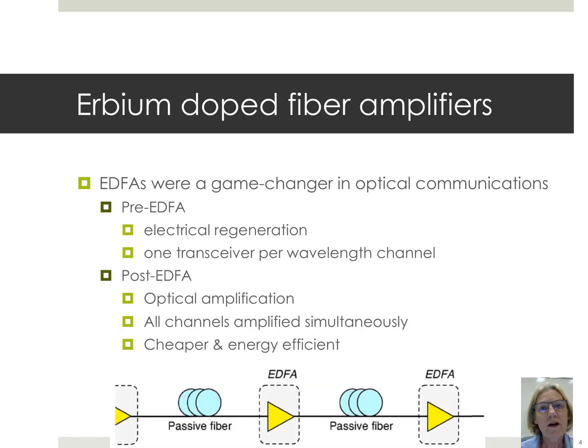So that was what I would call the first generation of optical communications. Then there was the development of a device known as the Erbium doped fiber amplifier, or EDFA. And EDFAs were real game changers in communications. Before the EDFA, we had this electrical regeneration of signals. Every partial link after the fiber, you would convert from optical to electronics, get your electronic bits, and then regenerate them in light for the next transmission.